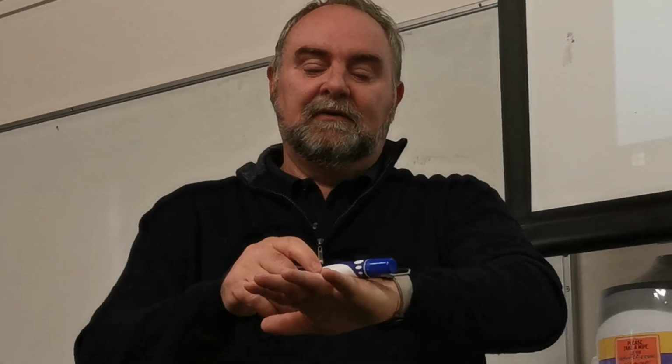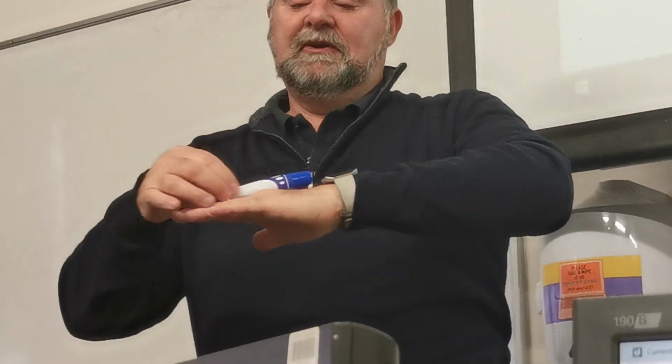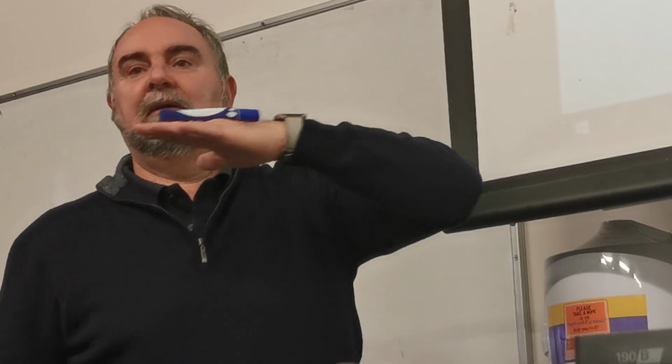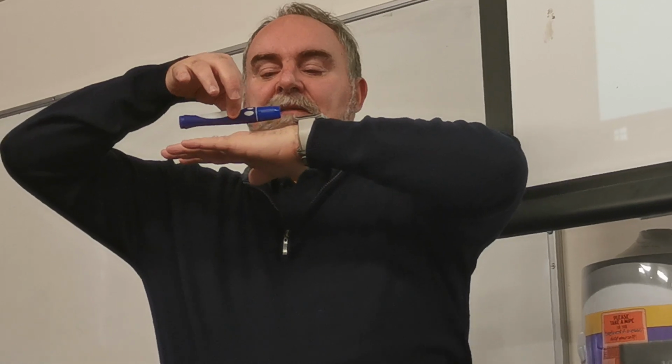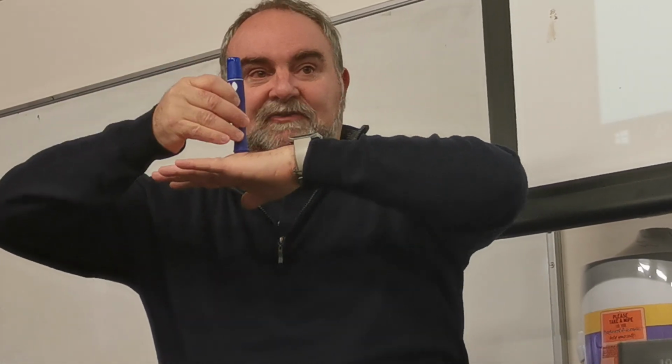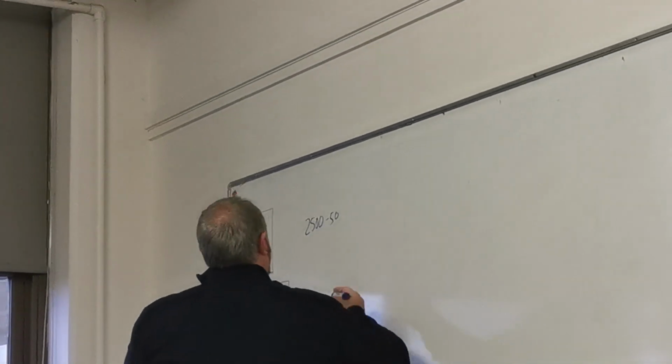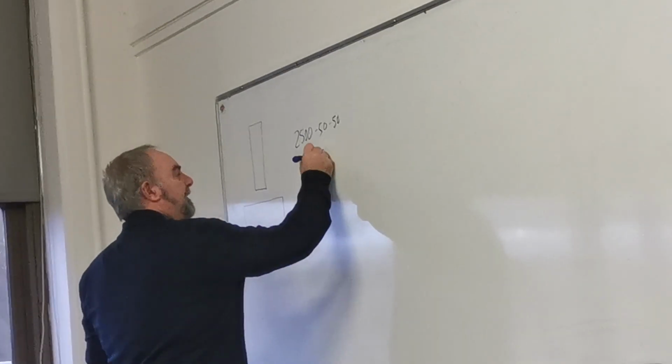We can't have a bar resting on the construction joint because it'll be resting on the concrete you've just poured and you won't get any concrete underneath it. And that's the whole bar, and it's 5 metres long. You'll see that, that's too much. So when the bar's running that way, we have to lift it with the 50 mil cover. If the bar is like that, it can rest on the construction joint. There's only a little bit of the bar that's sitting there, okay? So 50 mil cover, so we take 50 off the top and 50 off the bottom. So we end up with 2,400.